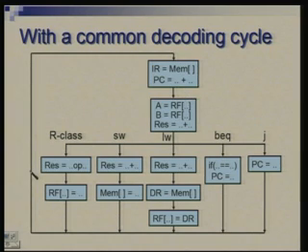This whole thing is called the instruction cycle, and within this you have clock cycles. An instruction cycle would require 4 clock cycles or 5 clock cycles or 3 clock cycles as the case may be, that is in this particular design. But there are of course machines where this range of number of clock cycles could be much more varied.